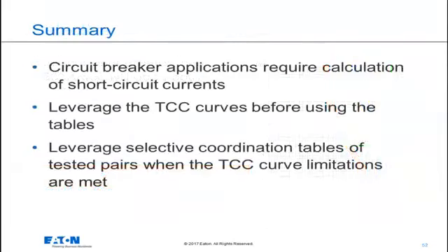In summary, circuit breaker applications require calculation of short circuit currents. We should always leverage the TCC curves before using the tables and leverage the selective coordination tables of tested pairs when the TCC curve limitations are met.